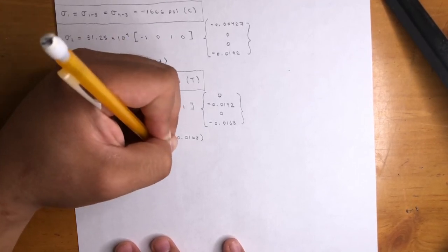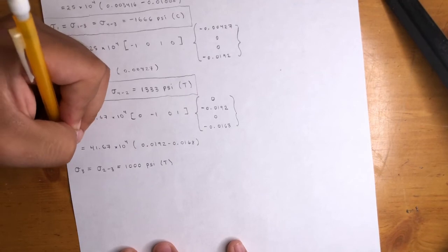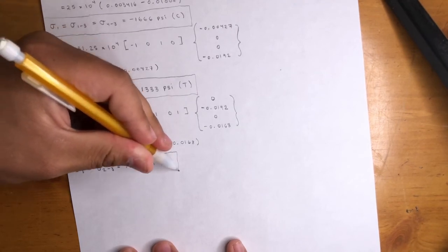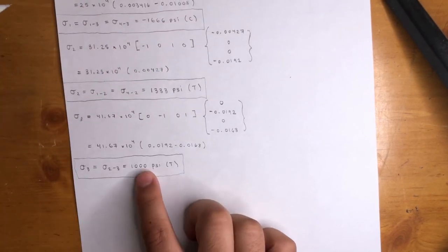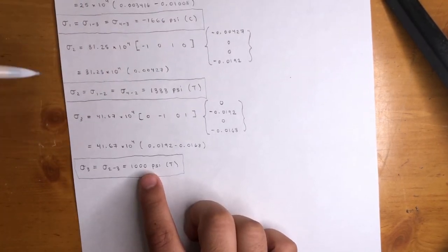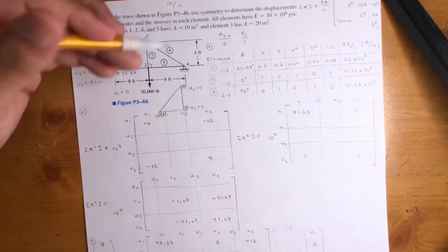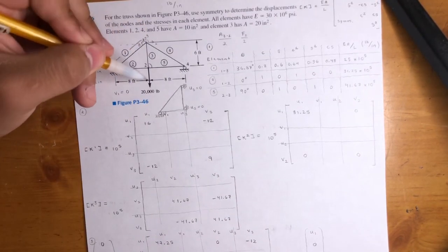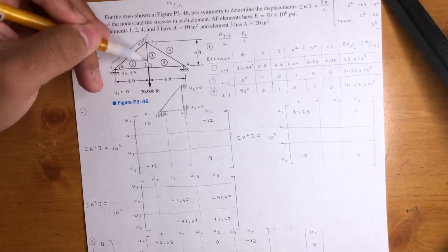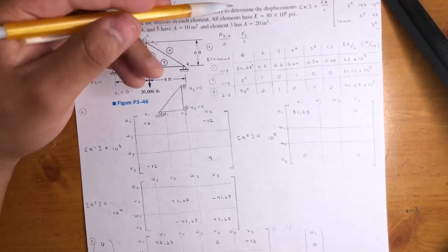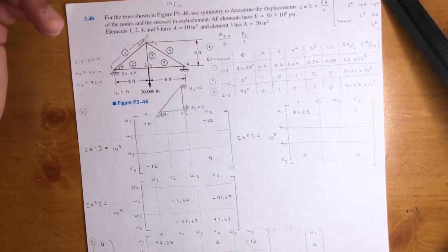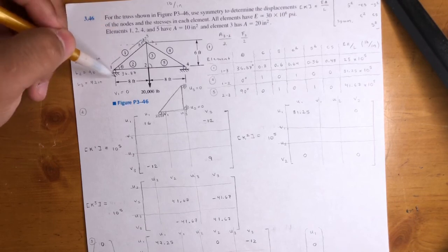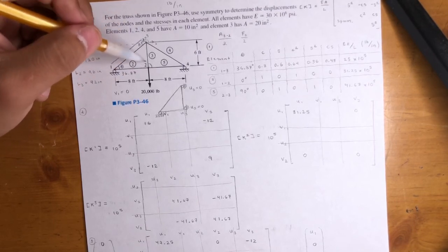Now you really can't verify your answers with the other stress values, but you could do it with this one. This is what I was talking about. It's 1,000 psi stress, right? Force over area is equal to stress. Since it's being applied along the axial direction, that means 20,000 divided by the cross-sectional area, 20,000 divided by 20, is 1,000 psi. So that makes sense. You really can't do it with these, right? Again, it's a little bit more complicated, but at least if you can verify that, you'll be all right.